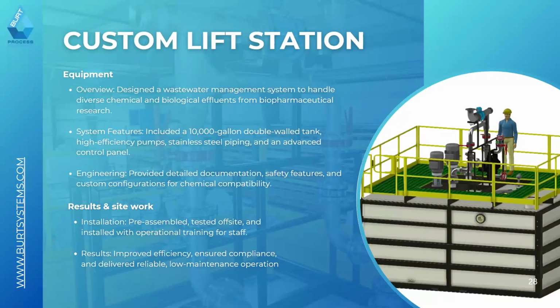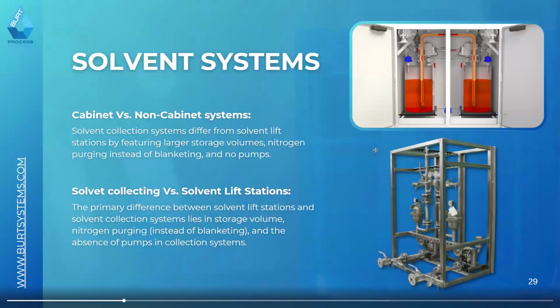It fundamentally changes how you make a lift station at that point. Because rather than trying to evacuate, you're essentially turning into more of a pH adjustment, equalization, transfer system design. Kind of touch on a few different specialty topics here.